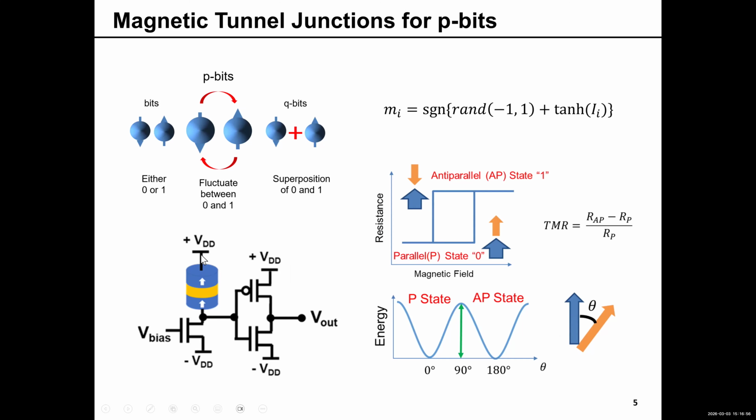Yes. So basically, the magnetic tunnel junction is what I'm highlighting here. So essentially, it's three layers. Usually, each of these has sublayers within it, but it can be boiled down to two ferromagnetic layers separated by a dielectric in between. So the conduction between these two ferromagnetic layers occurs through tunneling.